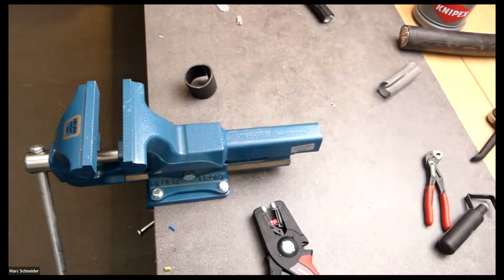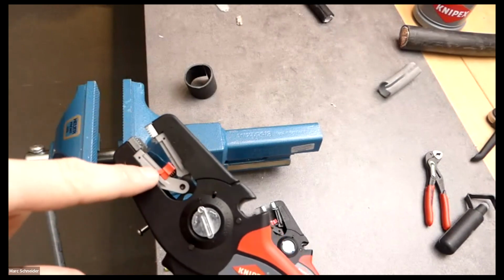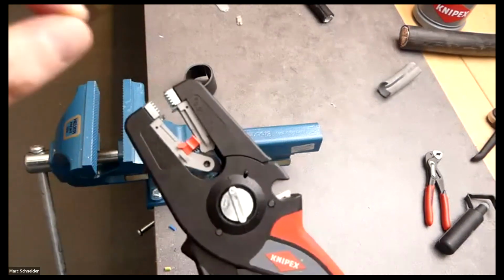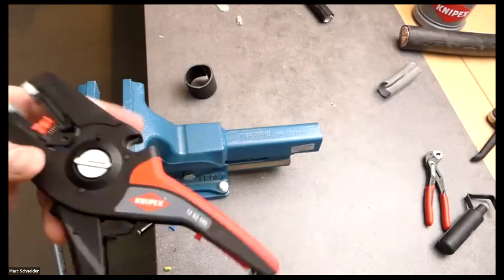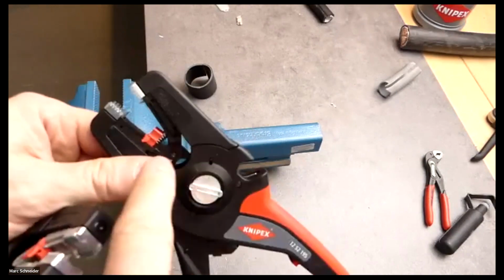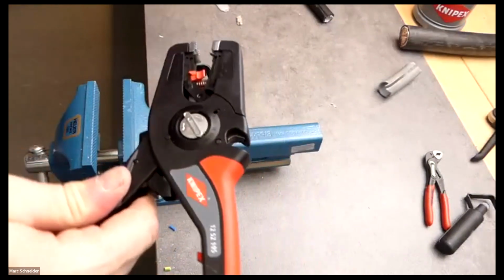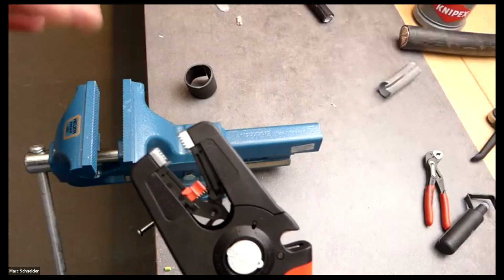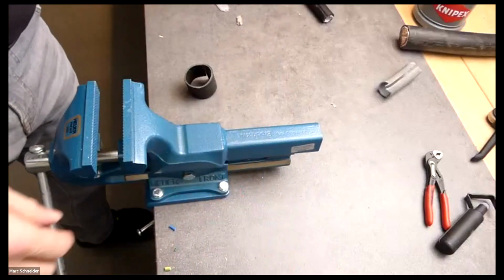We have also in our range a special blade block with information. This has a special article number. So this blade block goes from 4 to 16. It's only for halogen-free cables with a very hard insulation. So again, you buy this tool, article number, and you have the black normal block from 0.0 to 16. And if you feel it does not work for the type of cable, maybe they're halogen-free, then you can order a second special blade block. So this was the preset 16.